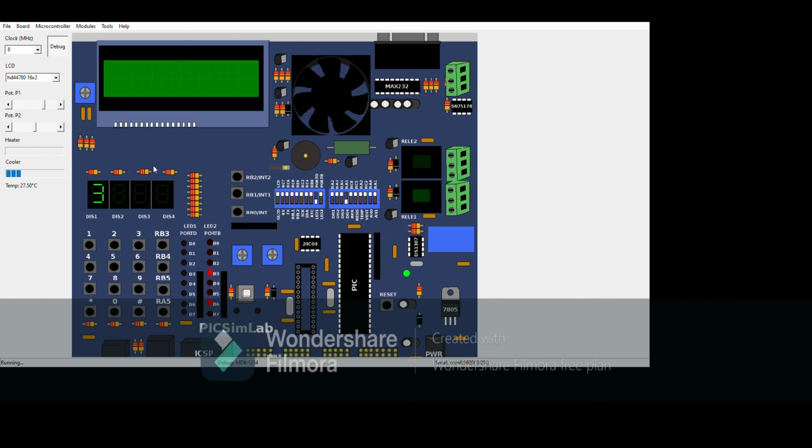When it is over the range, equal to 1.5 volts or greater than 1.5 volts, the display will show 3, and the LED that we simulated during the second state will now turn off, and another LED will light up. And the LED B3 will remain lit here. At the same time, the PWM is generated to switch on the fan.